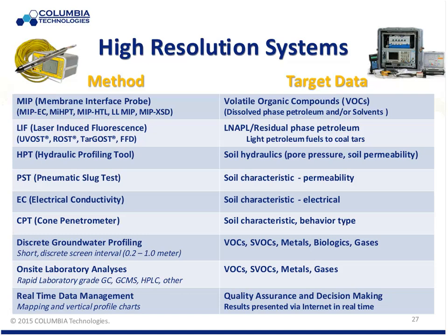Electrical conductivity or soil resistivity has been around for decades. It's frequently employed on a lot of these tools to give us a feeling for soil types. It is affected by a number of other types of situations in the subsurface, so it by itself is not a straight soil typing tool. Cone penetrometer, again, has been around decades, gives us geotechnical or physical parameters of the soil, what they behave like in terms of stresses and pressure capabilities.